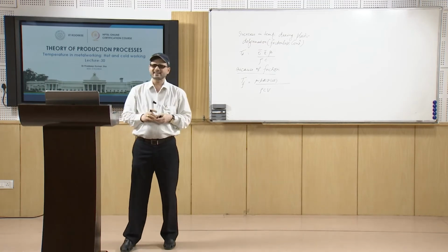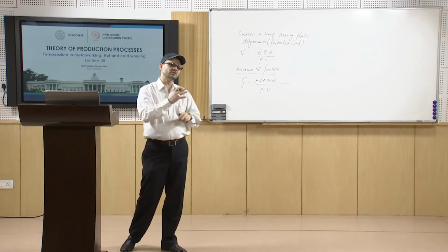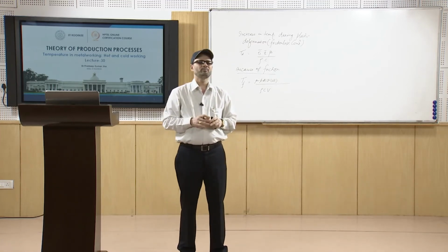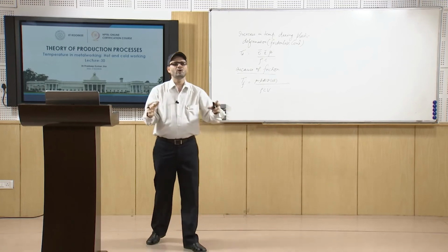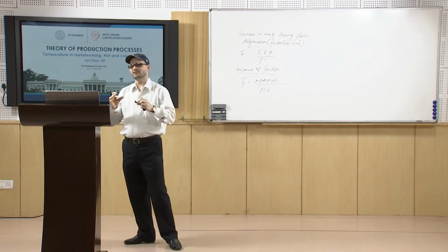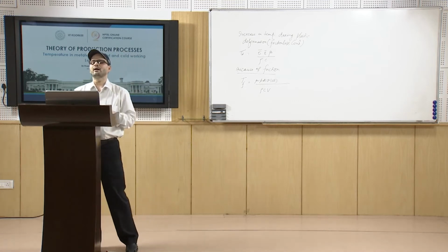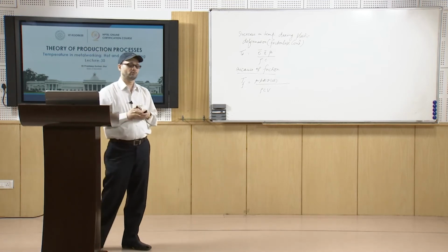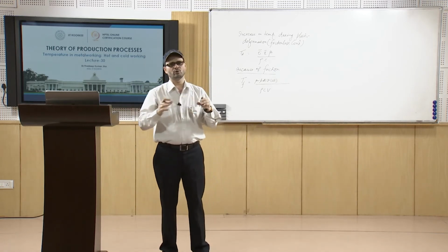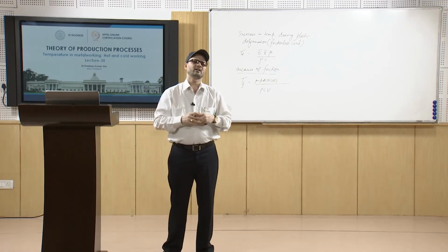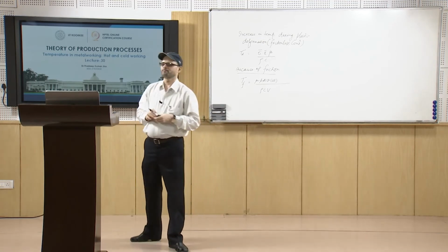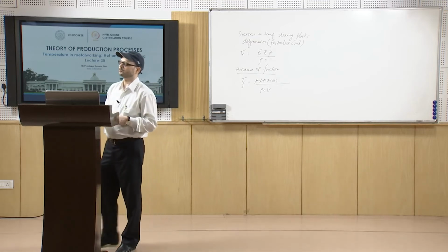So, in that case the chemical inhomogeneity inside the material is minimized. So, the material will be more and more chemically homogeneous. Another thing is that because of the deformation, the blowholes and porosities are basically welded up. So, blowholes and porosities are minimized. This is another advantage of the hot working processes.